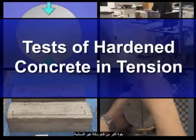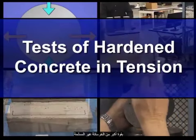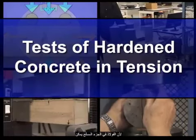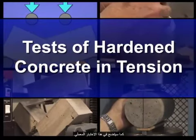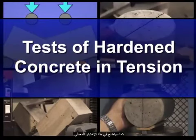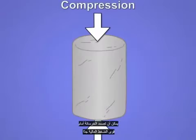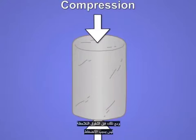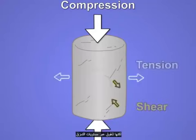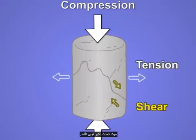Reinforced concrete has greater strength than unreinforced concrete because the steel in the reinforced section can be used to carry large tensile forces, as will be demonstrated in this laboratory testing. Concrete can withstand very large stresses under uniaxial compressive forces. However, the failures observed are not compressive in nature, but failures along shear planes where maximum tensile forces occur.